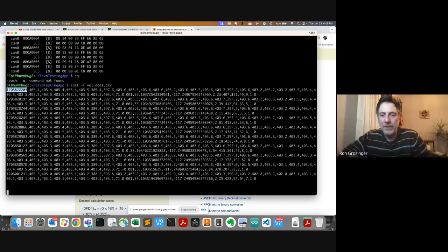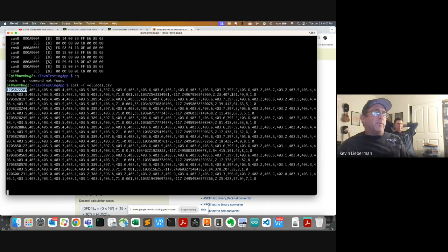That's pretty cool. Have you done any analytics based on that? Did the GPS or the current sensor help you out? Yeah, absolutely. Especially in the beginnings of this car, I'd go back and I had a script I made that would graph this all out. Graph my battery voltages along with my current, and then I can refer back to where I was, latitude and longitude at the time too.